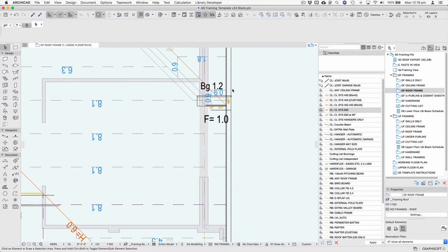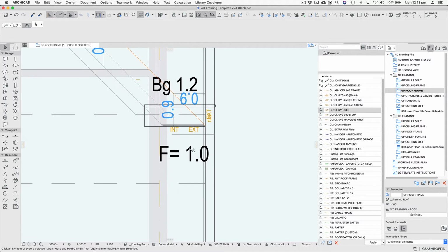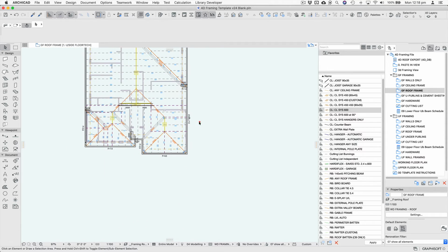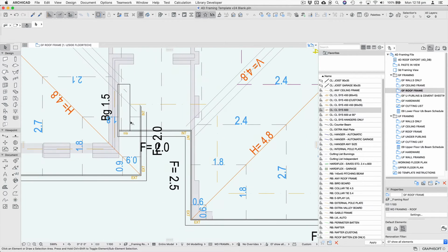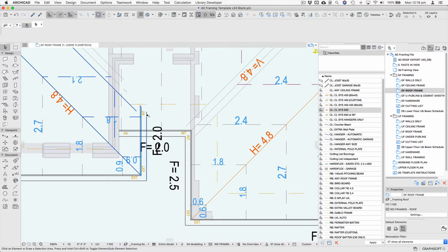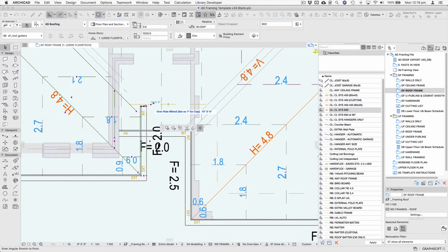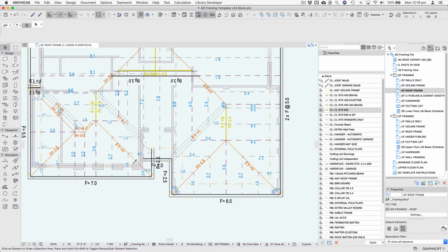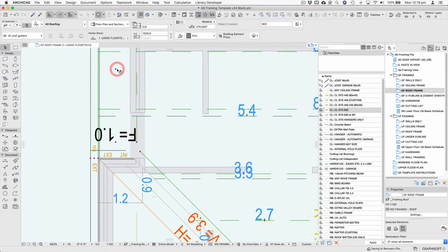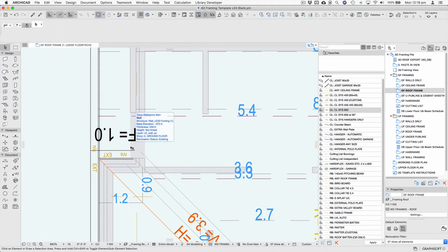You can see there's a barge being ordered through here, which is great, but the fascia is doing an internal joiner, so we want that sleeve to be non-existent. Through here we've got a barge there that doesn't need to be there. So I'm just going to remove the barge. Then we've got an overlapping gutter, that internal sleeve, just make that NA. And then last but not least, over here we've got a barge that needs to be removed. An internal sleeve for the fascia doesn't need to be there, and that's it.